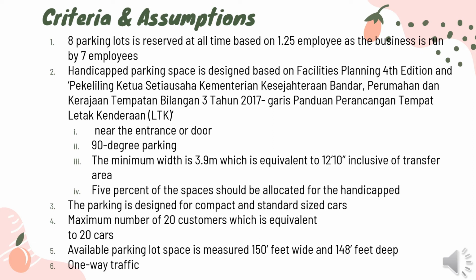The second one is handicap parking. We designed handicap parking based on Facility Planning 4th Edition and Pekeliling Ketua Setiausaha Kementerian Kesejahteraan Bandar, Perumahan dan Kerajaan Tempatan, which stresses that handicap parking should be placed near the entrance or door and use 90-degree parking. It requires a minimum width of 3.9 meters, which is equivalent to 12 feet 10 inches, inclusive of transfer area, and we need to provide it based on 5% of the spaces.